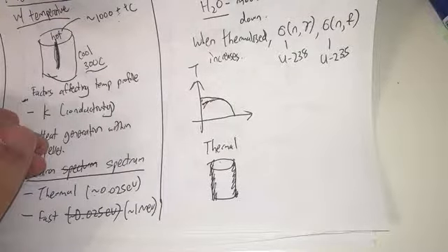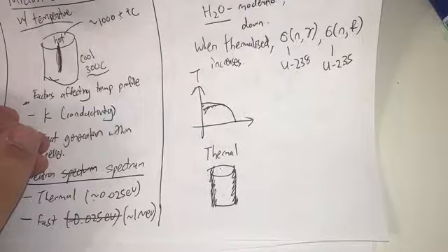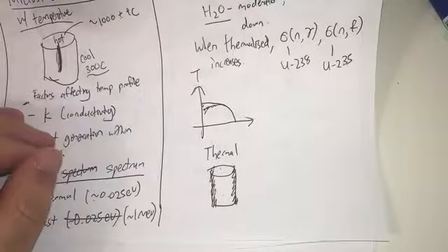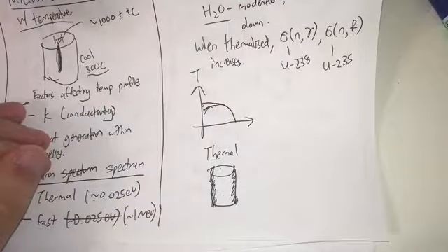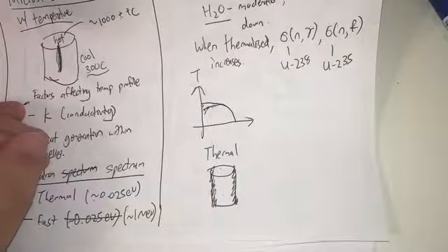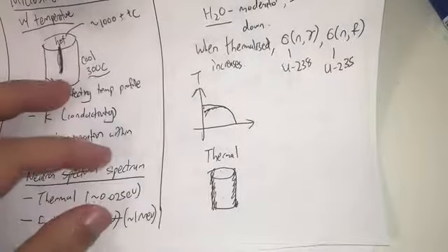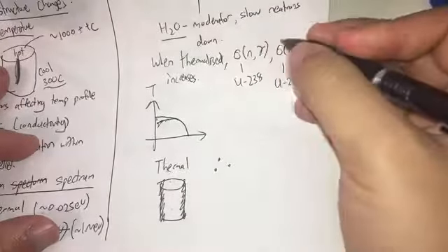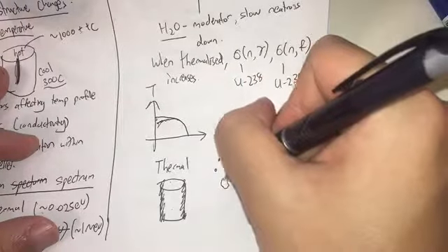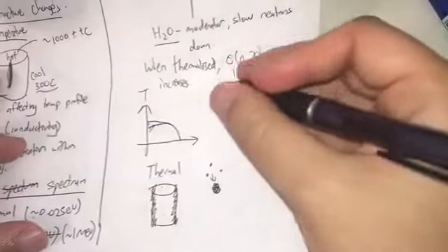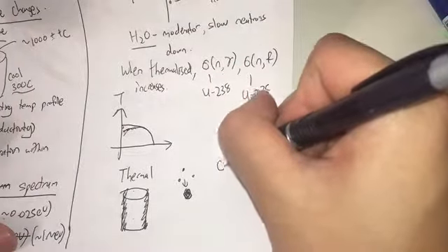Now, the result for this is that the microstructure evolution by temperature is relatively uninteresting compared to a fast reactor. You may have sintering and some grain growth in the center of the pellet, but nothing as dramatic as a fast reactor. So what is sintering? Sintering means that when you have very small particles and you heat them up, they will join up into a bigger particle. That's what sintering means. And grain growth is a similar concept.